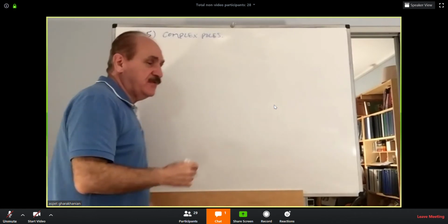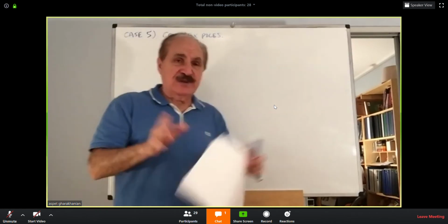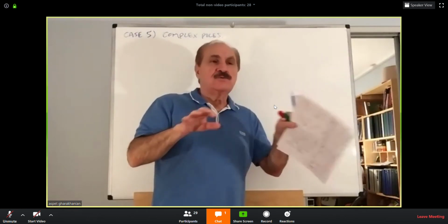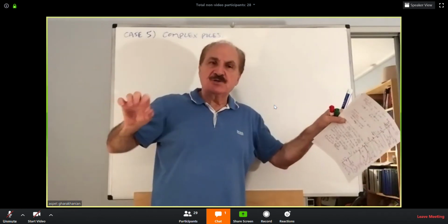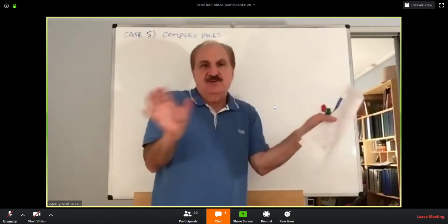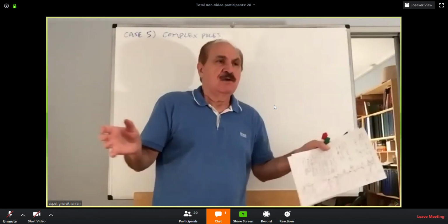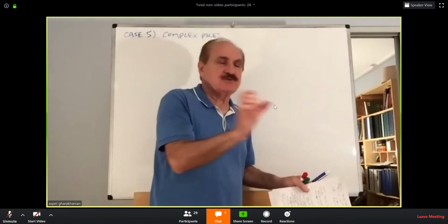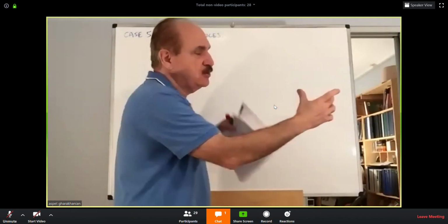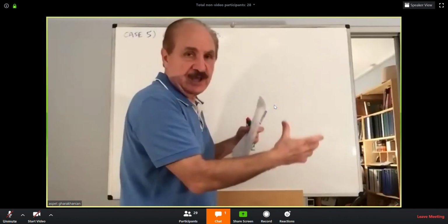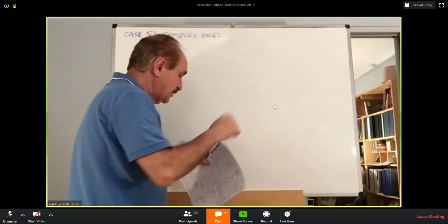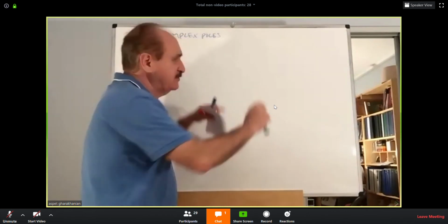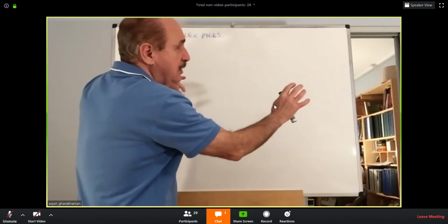First of all, if your transfer function had a second order denominator with two real poles, you could break up those two real poles into two separate single ones. That's easy. Then you could apply the same rules as we did for single poles for each one, and then look at the whole thing as a product. But with complex poles, it is impossible to break them up into two real poles.